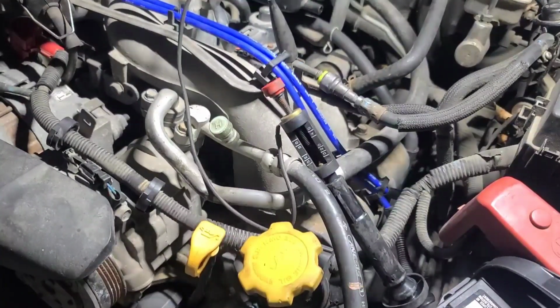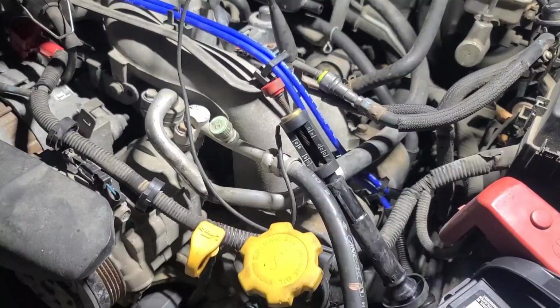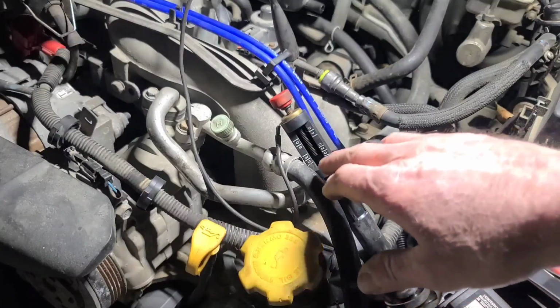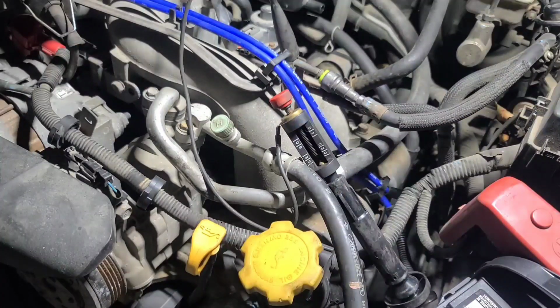Well, I'm definitely not hearing spark. I'm going to check that recording. So no spark at about 30,000 volts. So I adjusted it down to about 2,000 volts, about 1/8 of an inch. We'll see if we got weak spark.